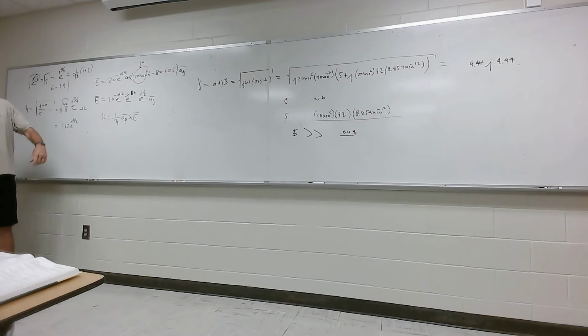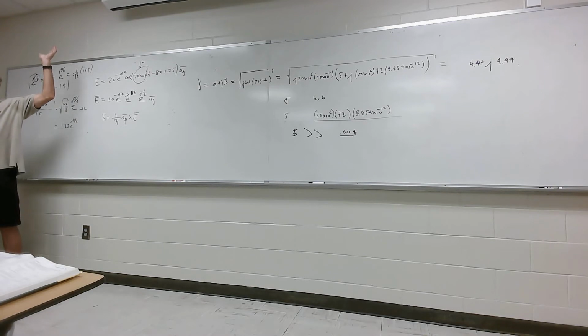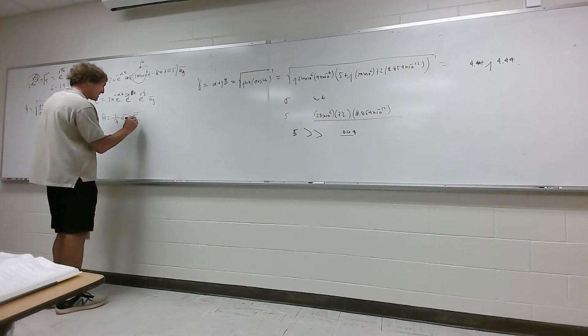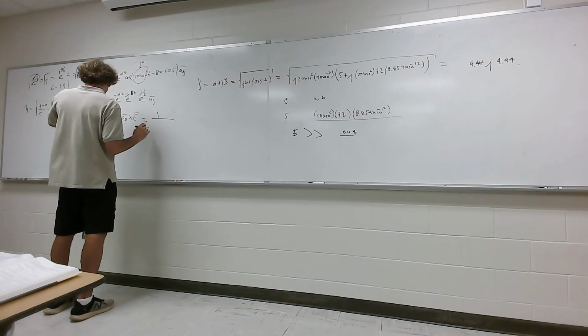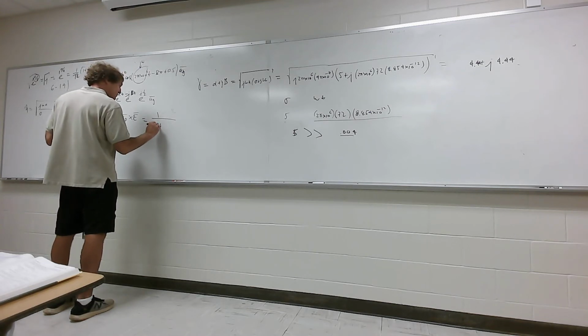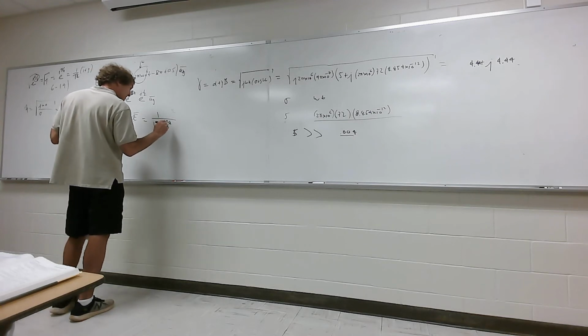We got the E field, we got eta. By the way, what's the direction of propagation? Let's take a look. How many see it's z, right? And therefore, a unit vector in that direction would be az. You agree with me? All right, so now I come down here and I say that's 1 over eta, so it's 1 over, don't forget the angle on this one, 1.25 e to the j pi over 4.